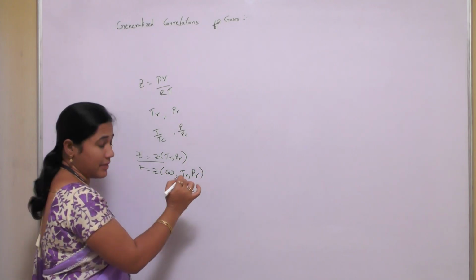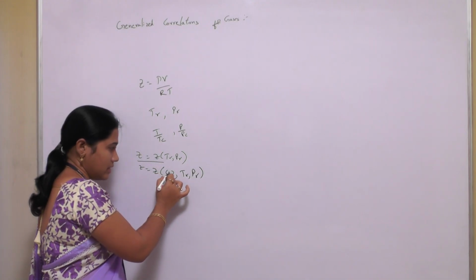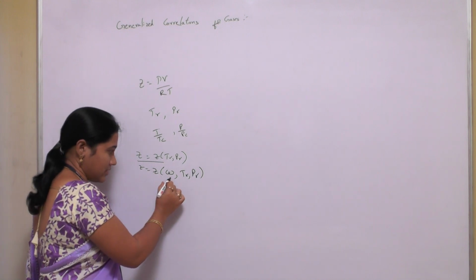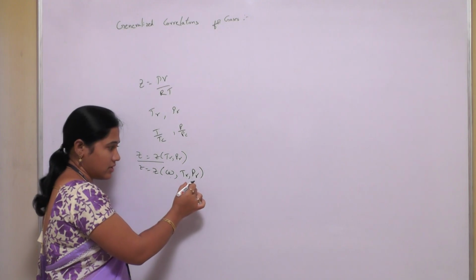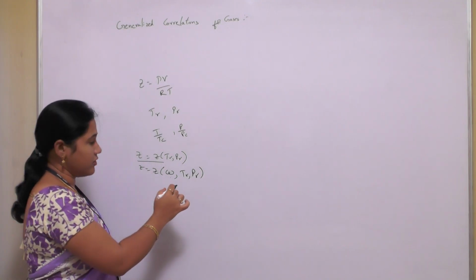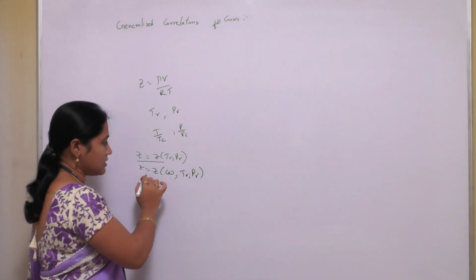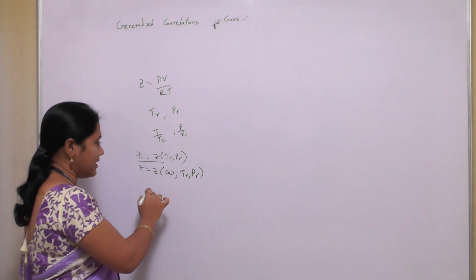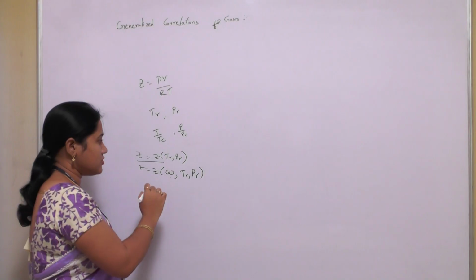This is the 3-parameter model. Omega is called the acentric factor. At the same acentric factor, temperature, and pressure, all fluids have the same compressibility factor and show the same degree of deviation from ideality. That is the law of corresponding states with 3 parameters.